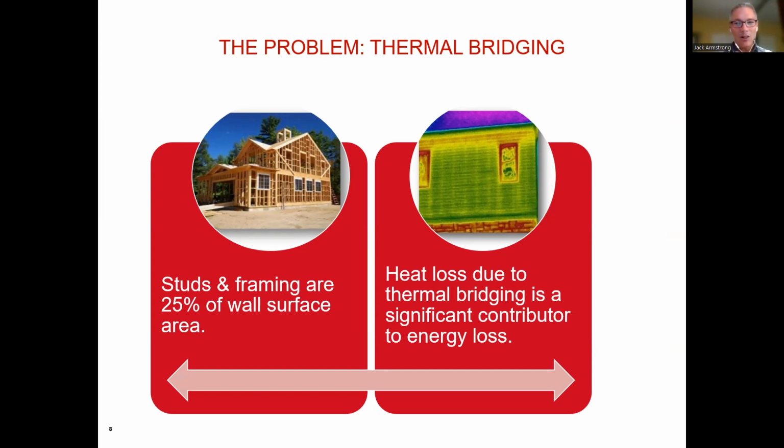If you add up all of those support structures on the external thermal envelope, that's about 25% of the wall area taken up by the wood structure. And there's no place for the insulation to go in only the remaining 75%.